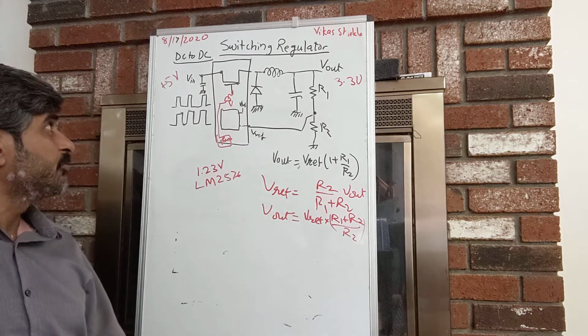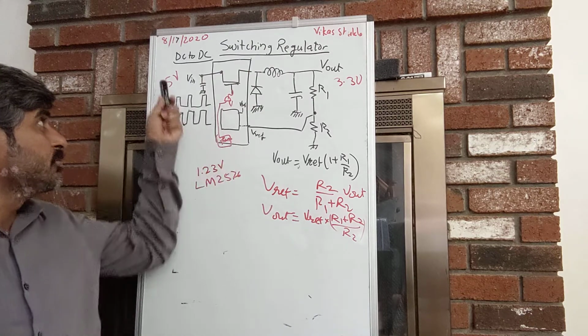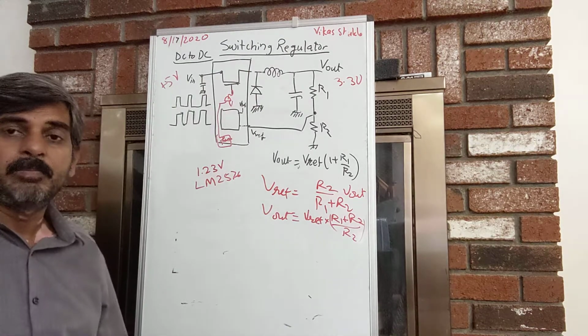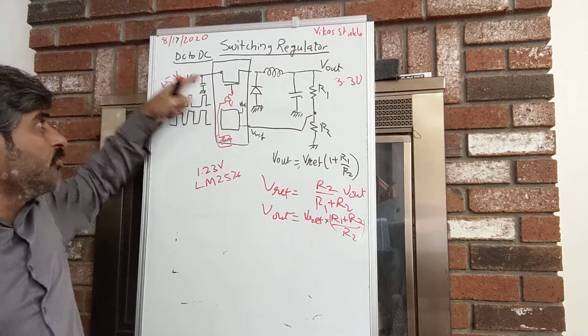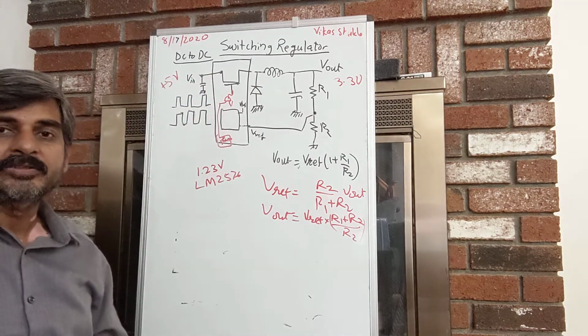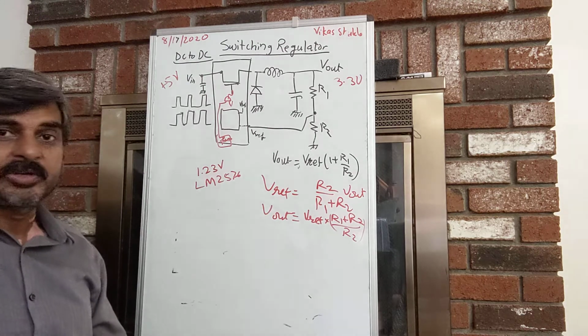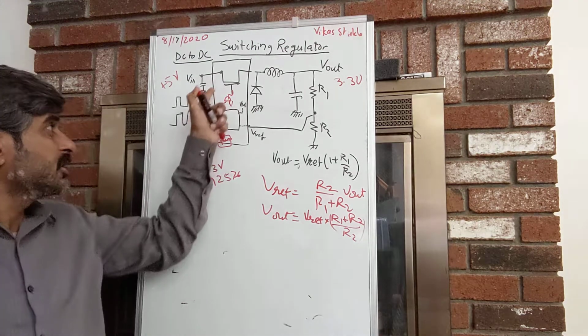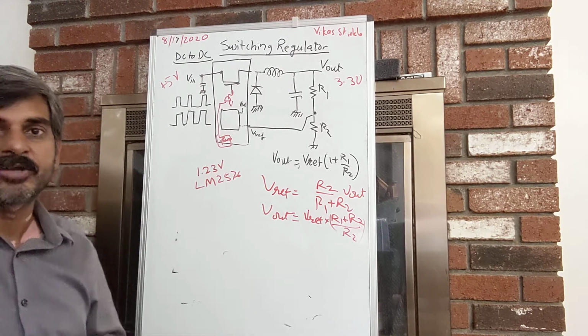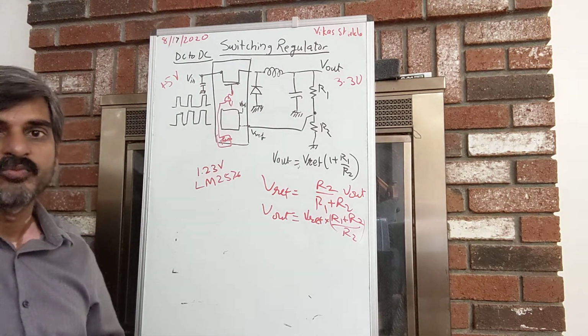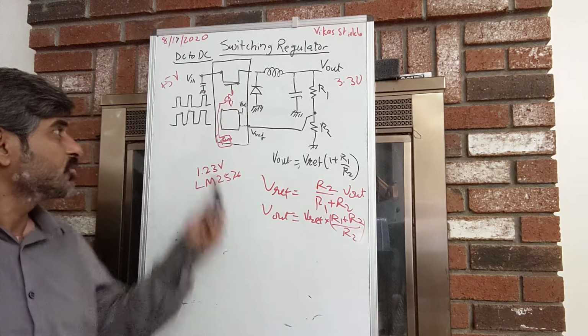Another thing this IC could be doing is the delayed start. So the moment you turn it on, they could have an RC kind of delay circuit that will turn this FET on only when some time has passed, for example 10 or 20 milliseconds or maybe more. So that's a second function this could provide.